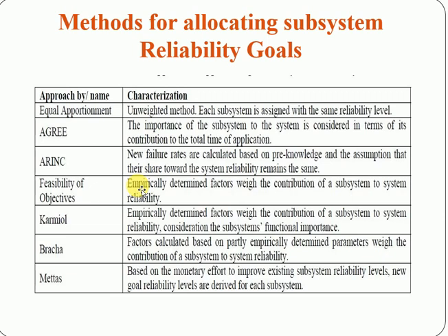The system reliability needs to be known. The failure rates of all components are assumed to be constant, and the system reliability structure to be either completely serial or completely parallel. Weighted methods share the commonality that they are able to derive subsystem reliability targets more accurately from the known system reliability level than the unweighted method. These factors stem from different scopes of consideration. The input information can be known or assumed. Weighted methods are more realistic and therefore have higher practical relevance.